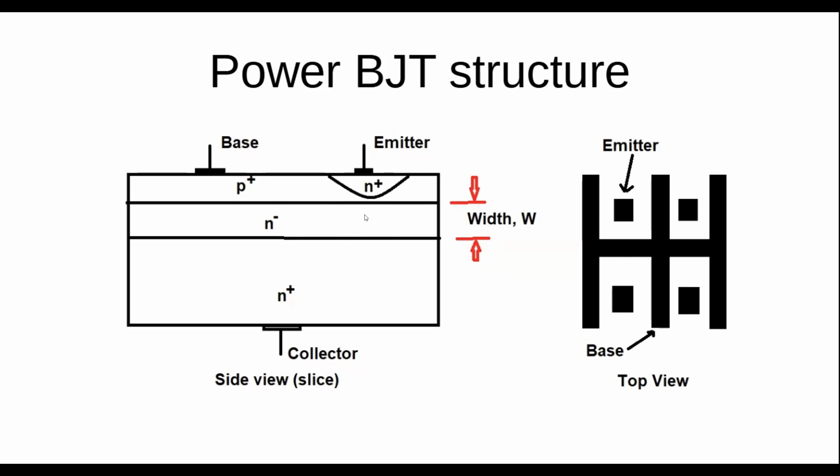To switch it off, I've got a lot more electrons to get rid of, to recombine, so that I can set up a new depletion region, which is what you have when you're switched off or in the cutoff region. So I would need to get rid of those extra electrons in here. And so that takes time.